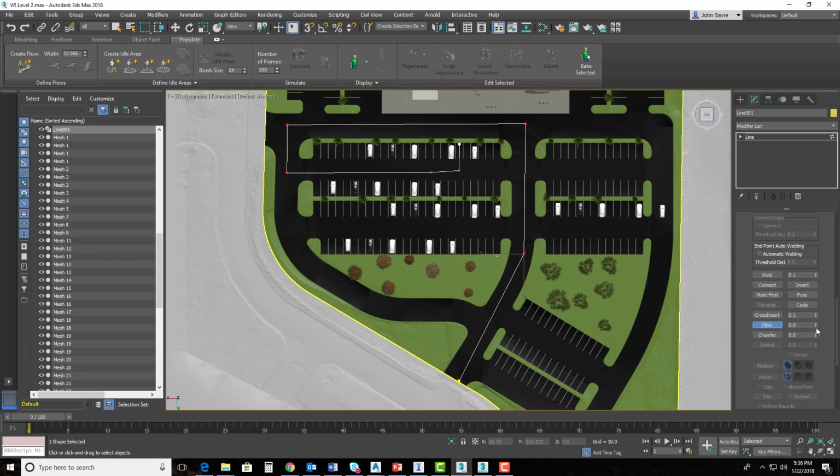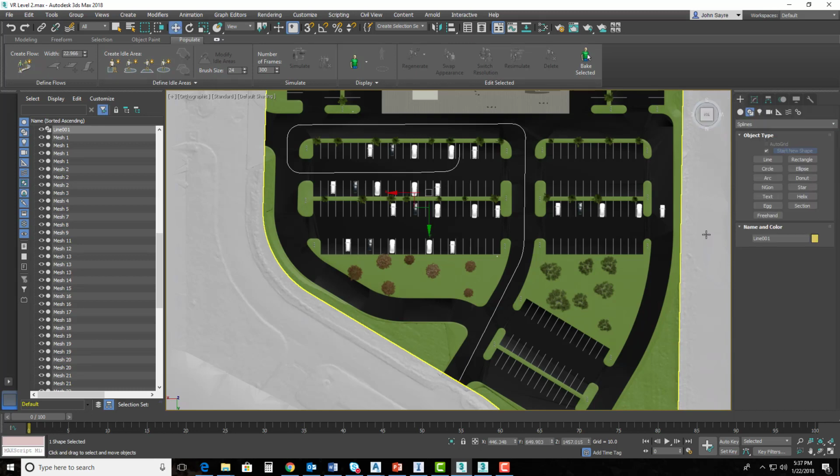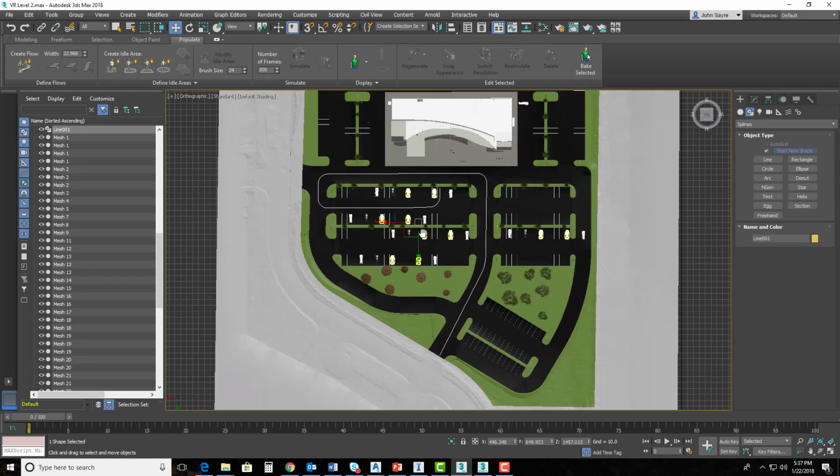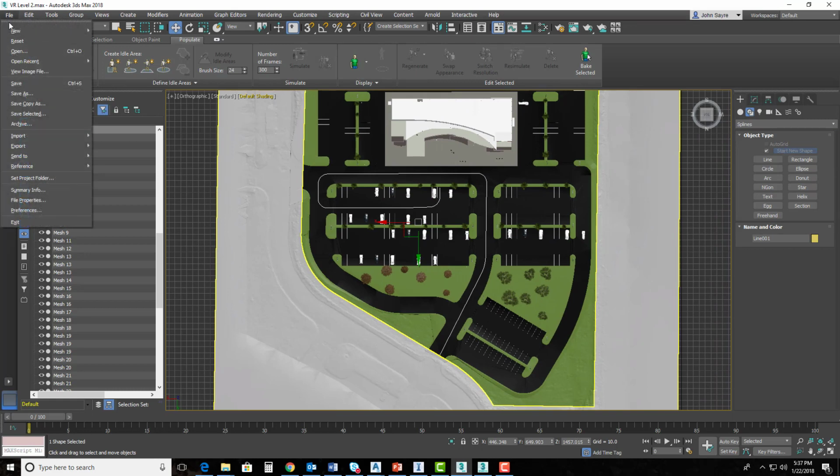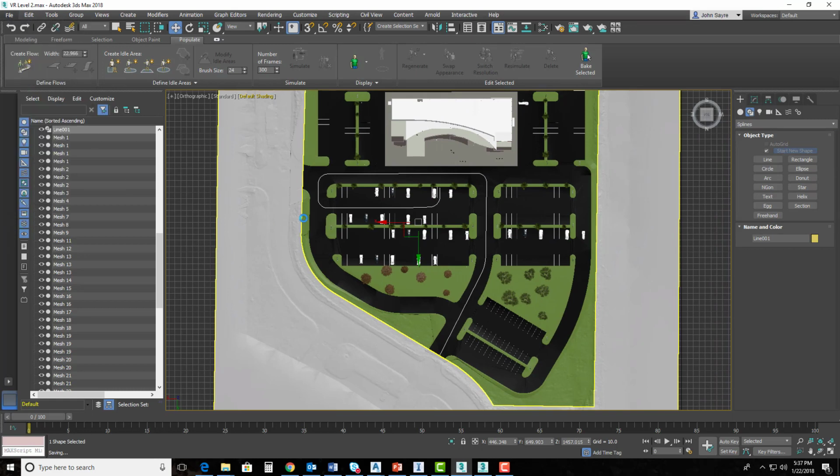Now I'm going to hold my left mouse click down over these arrows, and I'm just going to push up, and you can see it's adding curvature to my PVIs. All right, I just get it to where I want it, and I let off, and I hit escape, and I can actually just select the plus sign here, the create button, and it releases that line. And I'll go ahead and save. I like to make sure that I save my line work. If I do something I don't want, I don't have to create it again, so I make sure I save.